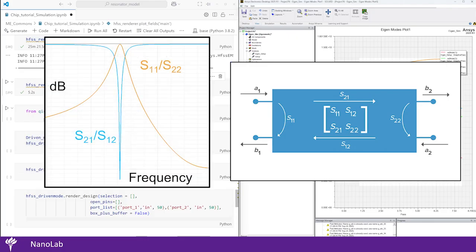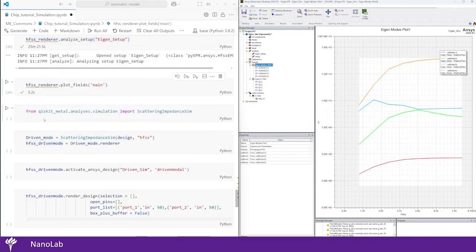When a signal passes through the feed line coupled to a resonator, at resonance, energy is stored in the resonator, leading to a dip in S21, which is a sign of less transmission, and a corresponding change in phase. Away from resonance, most of the signal passes through with little disturbance.